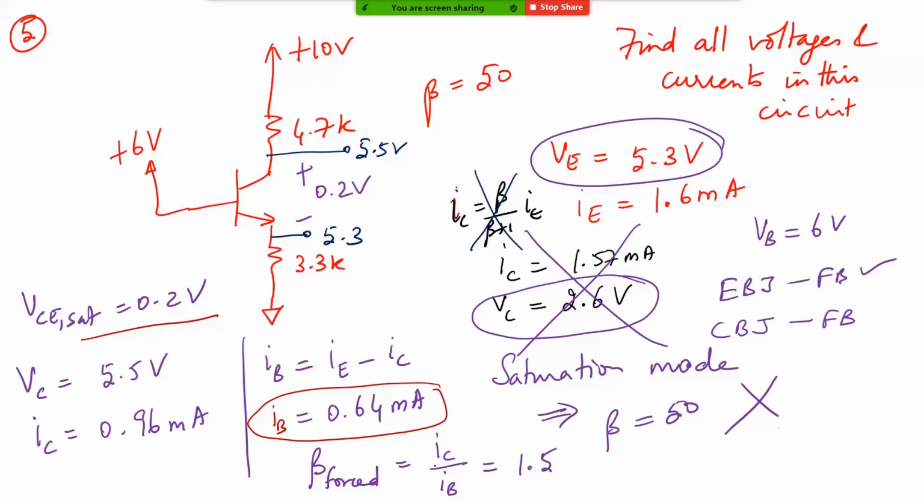Typically while solving these types of circuits, whether you're analyzing an actual circuit which you find on the internet and trying to find the currents, or designing your circuit and you want to know what is happening, or designing a circuit to be implemented practically in the lab, you assume that it is in the forward active mode, because for all amplifier purposes that is the region in which you want the transistor to be.